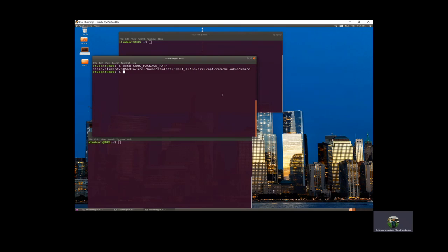Now, ROS has several commands that are very similar to the regular Unix or Linux commands. Let's take packages. We know ROS has several packages within the file system, and if you want to look for a particular package, find where it is stored and go into it, you can say rospack find and then the name of it.